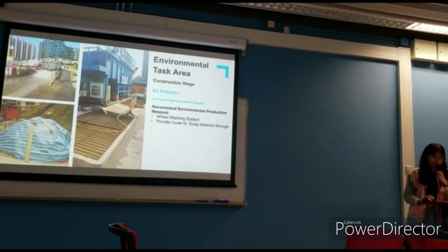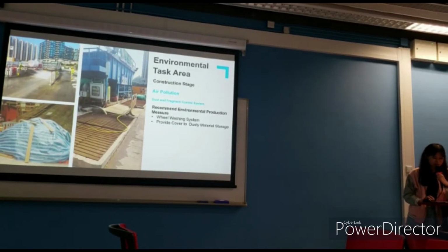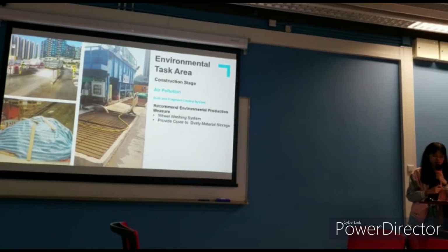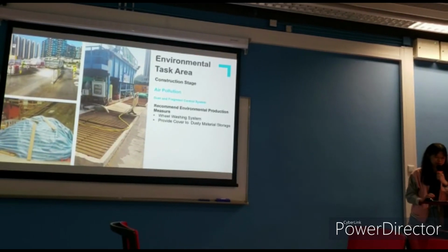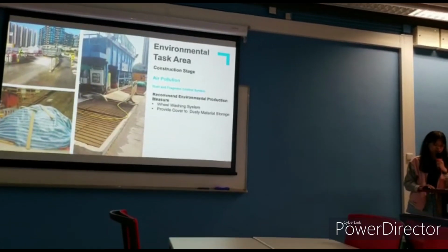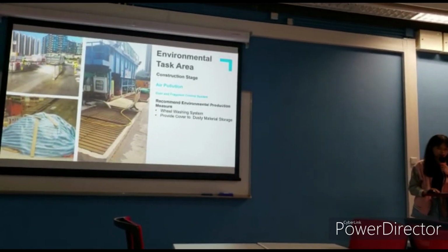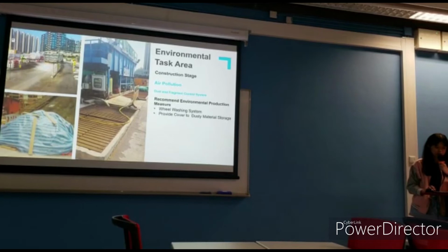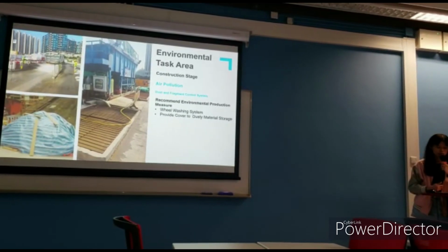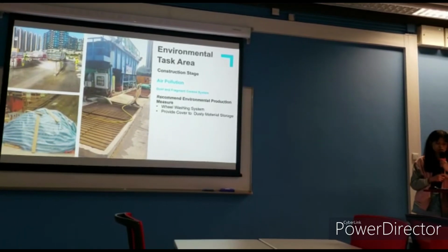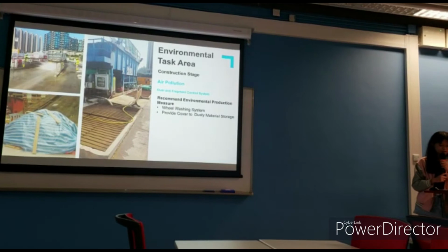There will be no more room on the site for soil storage during the construction, and therefore all excavated soil will be transported to another place for storage. During the soil transportation, the delivery trucks may bring dust and fragments to the Hankow Road, which may cause complaints by the public and a fine from the Environmental Protection Department. So the main pollutant for the air pollution will be dust, and dust control mitigation measures should be carried out in our project.